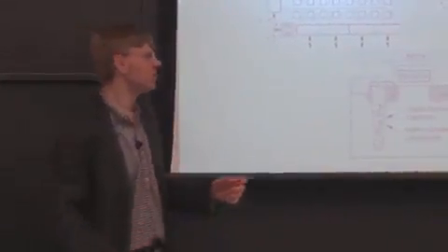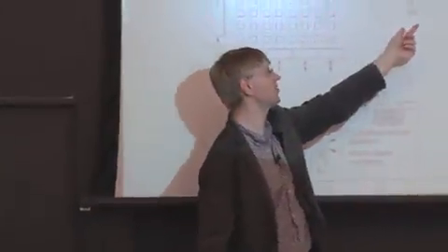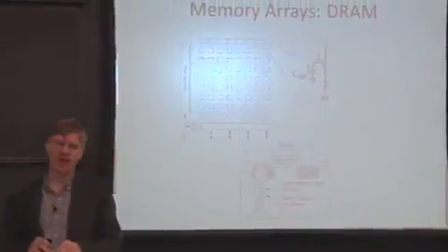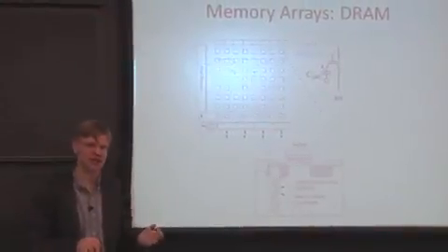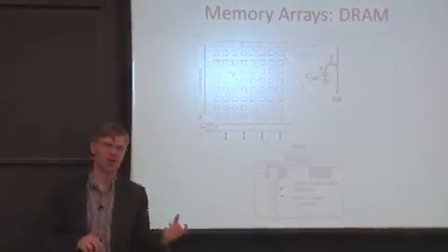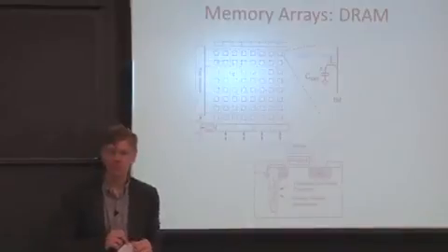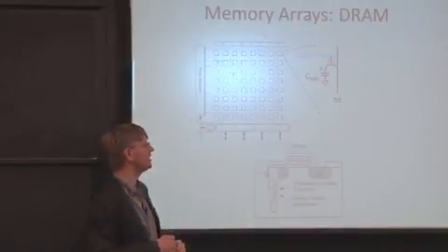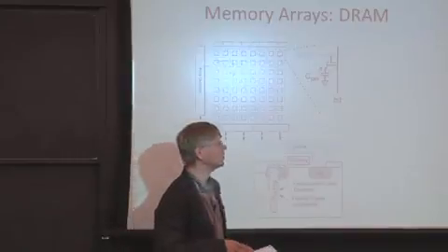And we still need something at the bottom here, which is very sensitive, to be able to read out this bit. The reason is that the capacitance you can store in one of these little capacitors is a very small amount, so there's not a whole lot of charge in the circuit. OK, so what are the problems with this cell?